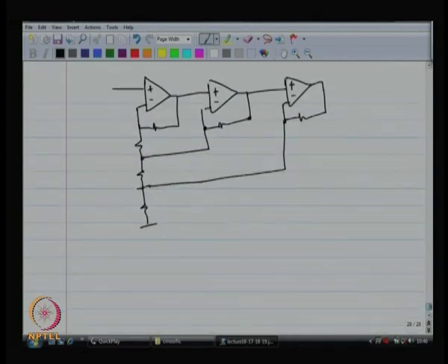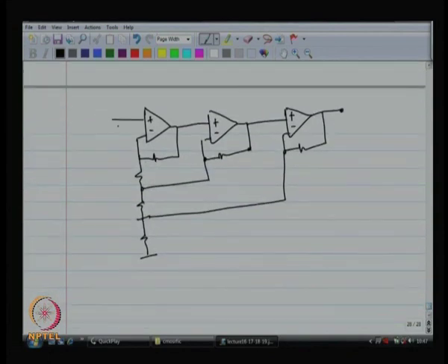Why not something like this? Okay. This also could be made, something looking like this could also be designed, and this also could be designed to have a gain of 1000, and this will probably have more bandwidth than what you have got over there. Now, you will not have the same location of the poles anymore, right. So, one can do all these things to get more bandwidth. Now, you replace this op amp that I have drawn over here with your favorite amplifying circuit, etc.